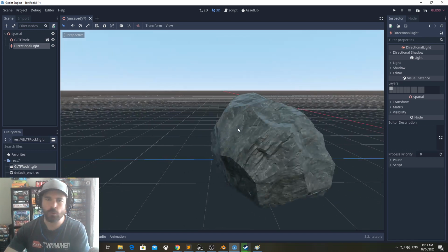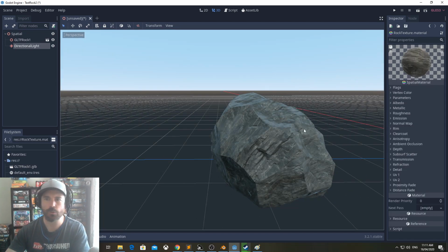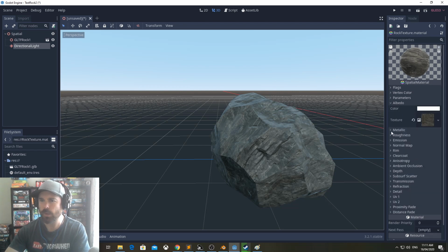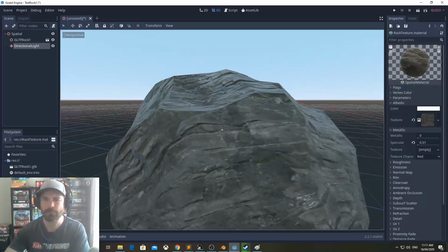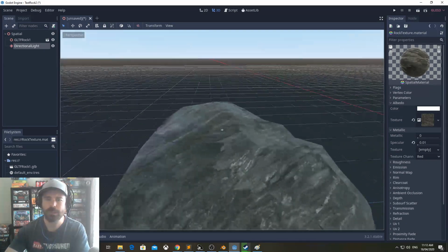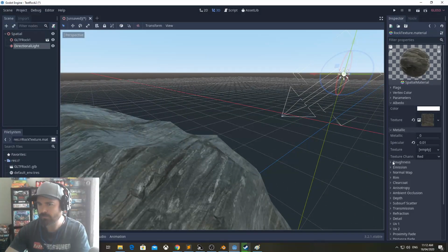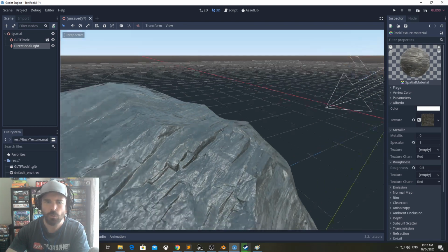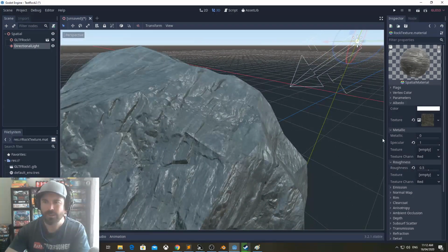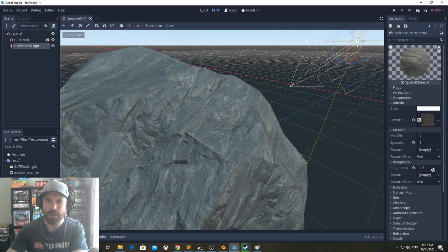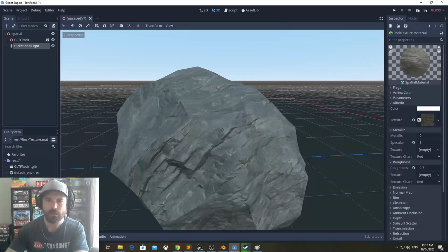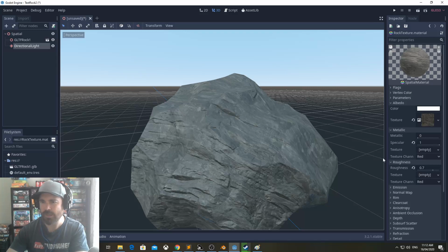Yeah, the wet look. Okay, so you have to edit the material for that, and you'll have to play around with the specular aspect of it. But it's depending on where the light is coming in, and its roughness. If you turn the roughness up, turn the specularity up, the specularity all the way up makes it look kind of wet. And if you turn the roughness down, it makes it look really wet. But if you turn that roughness up, it'll look less wet. So you have to kind of play around with those two settings there in the material that comes in.